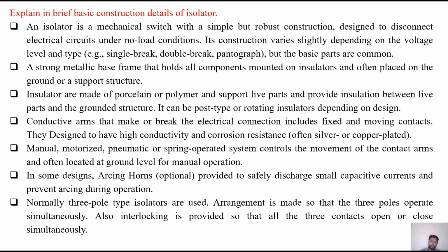Normally, 3-pole type isolators are used. Arrangement is made so that the 3 poles operate simultaneously. Also, interlocking is provided so that all the 3 contacts open or close simultaneously. So this is the basic constructional detail of an isolator.